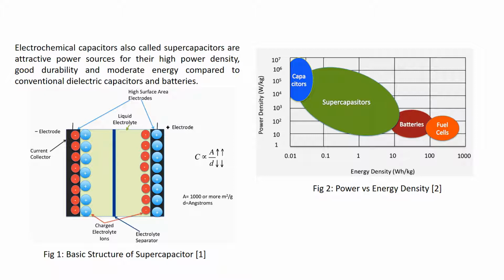When we charge the supercapacitor, the negative ions and vacancies on the positive electrode side and the positive ions and the electrons on the negative electrode side are arranged across the interface. This state of arranged ions and electrons is called an electrical double layer.